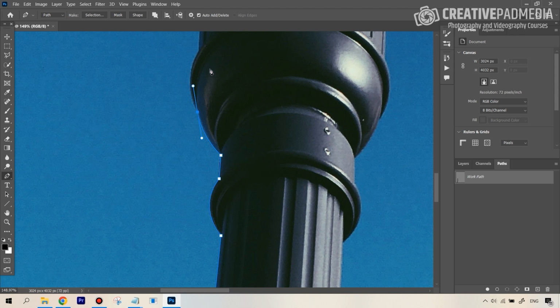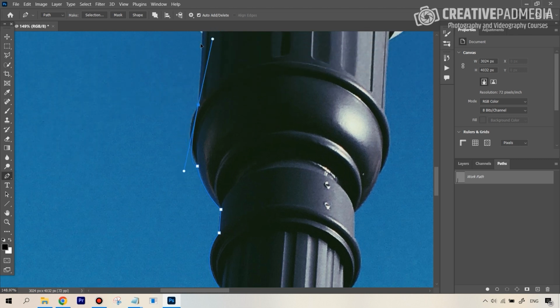So again, if you want to do this destructive way, because this is easier to understand, what will I do here before I go on? I'll just delete this by holding down Alt Option, and then continue this and pull it out. So this is kind of destructive because you are removing that handle like this, Alt Option and like this. I'm going to undo things.